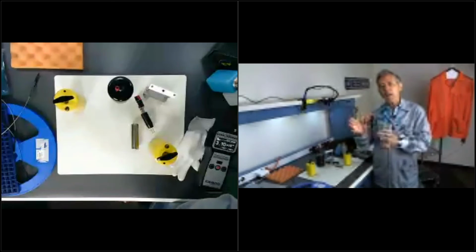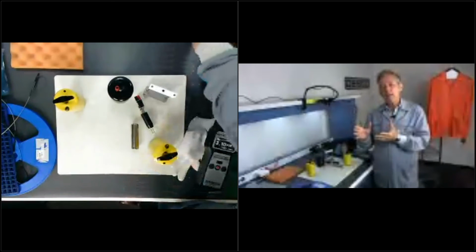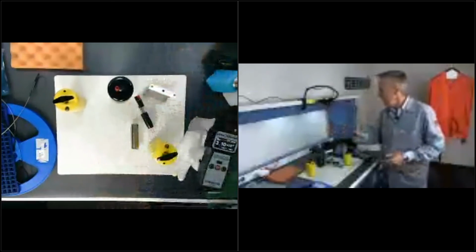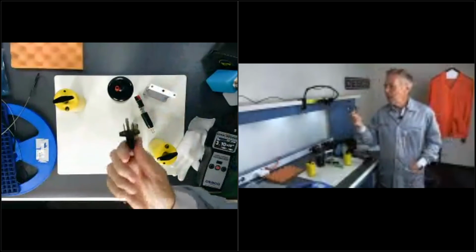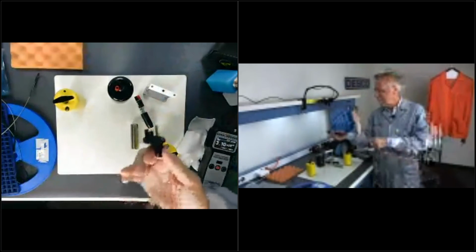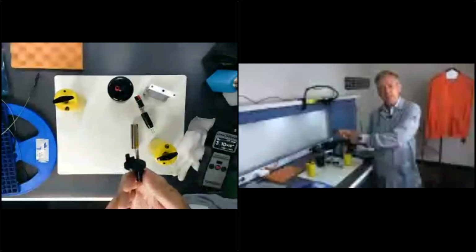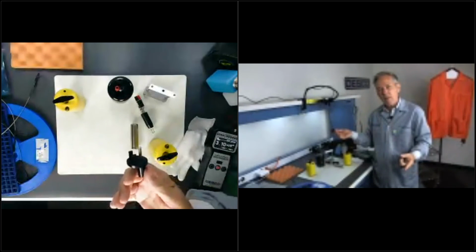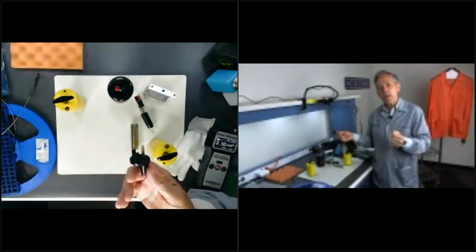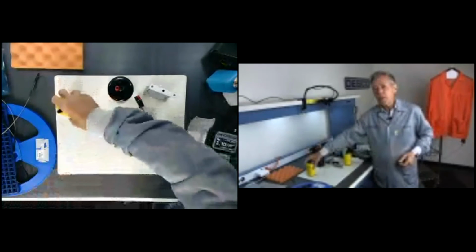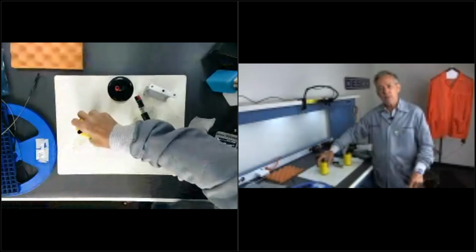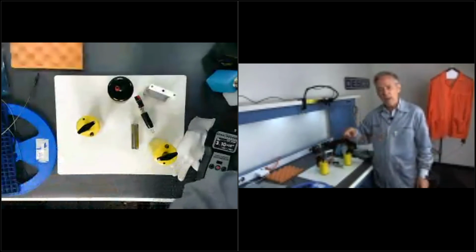So if your floor is grounded like that, I might just use this handy little checker here to plug into an AC outlet and plug the black lead of my tester into that. Now that's resistance to ground. But if it's a separate ground rod coming up through the earth, I would attach my ground lead to that, with my other 5-pound weight on a section of floor, and that is my ESD ground.